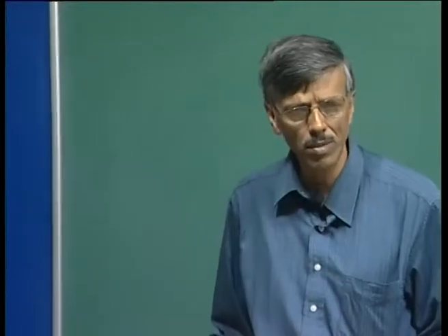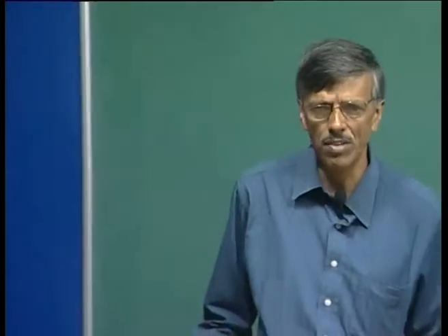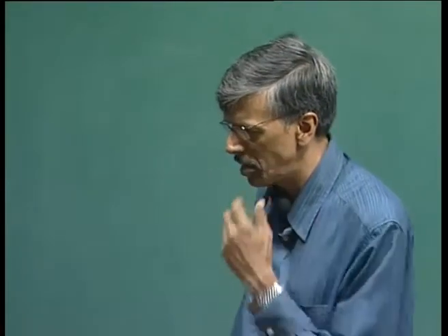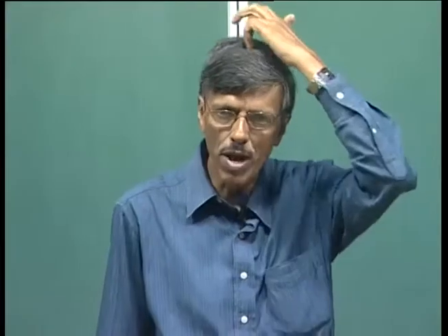Now, you see, we have talked about the historic development of the subject per se, that while the German school was very vehement in their pronouncement that there is an instability problem, experimentally it had never been obtained. One of the experiments was done by G.I. Taylor, and what he did was he took a flat plate boundary layer, and in the middle of the tunnel put in a kind of vibrating bump, oscillating at a fixed frequency, and he could not detect any wave solution, and he pronounced that this theory would not be correct.